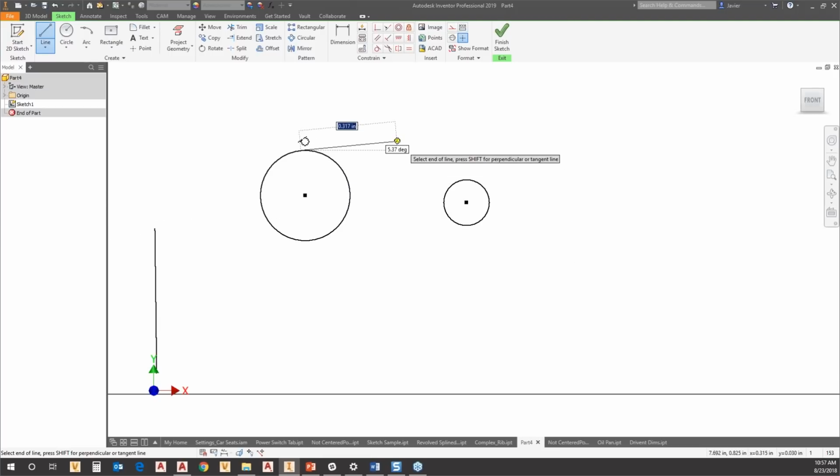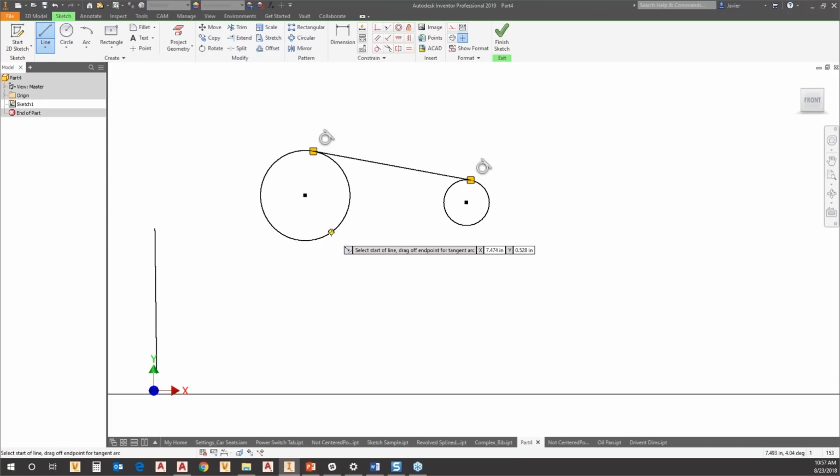So I'm holding down my shift key, and now I can connect to this arc and wait for that tangent symbol to show up. Those inferred constraints, pick. Same thing here: I'll pick anywhere, no shift, nothing. Now I'm holding down my shift key. It's now tangent, and I can connect this and make basically another sort of slot, but without these even diameters.